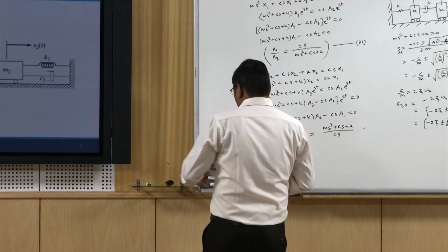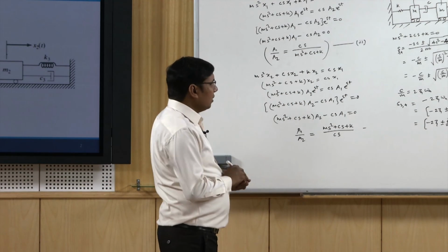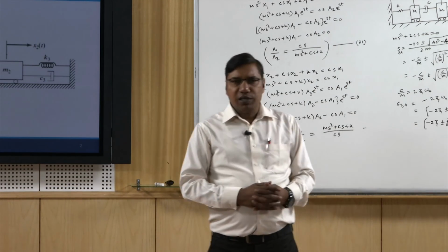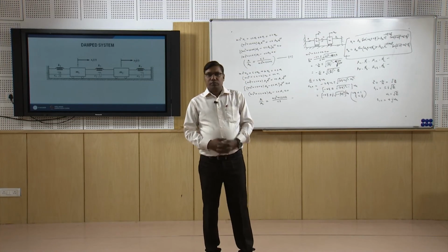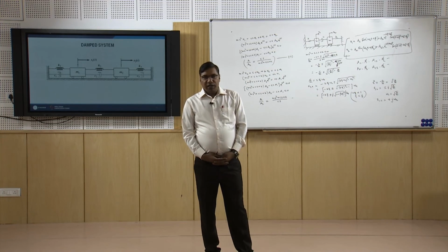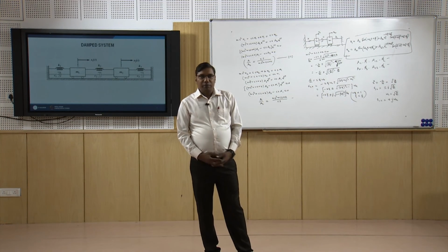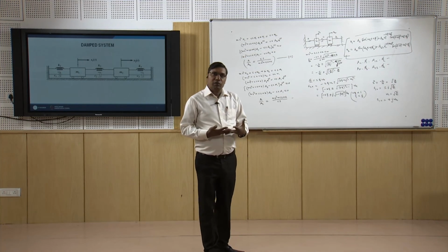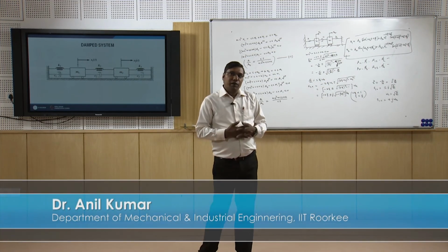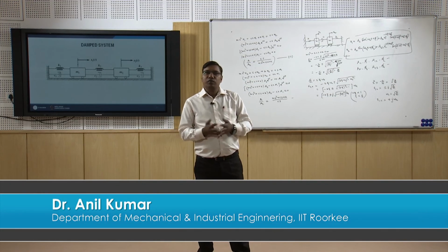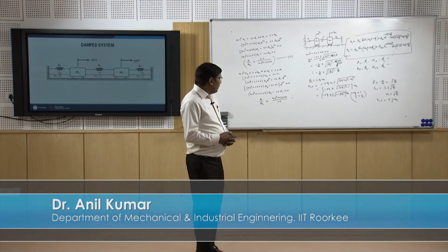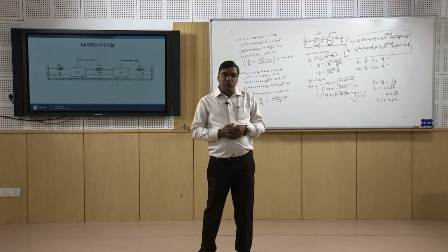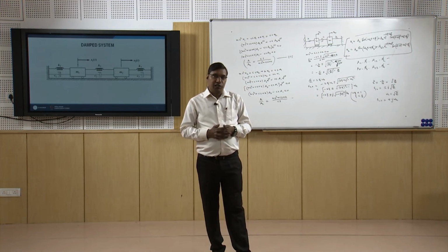Okay, so that is how we can study the damped vibration of a 2 degree of freedom system. In the case of the first natural frequency, the damper is ineffective. There is no role of the damper, because both masses vibrate as a pure sine wave. But in the other case, the damper is effective with a damping factor of 2 zeta.